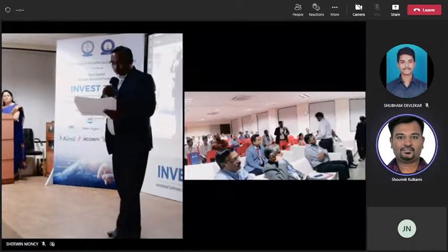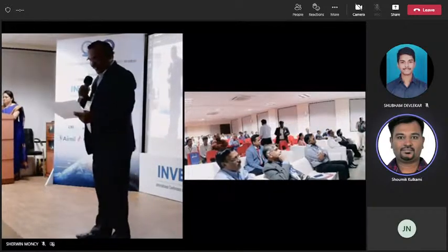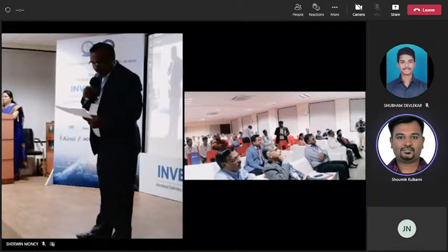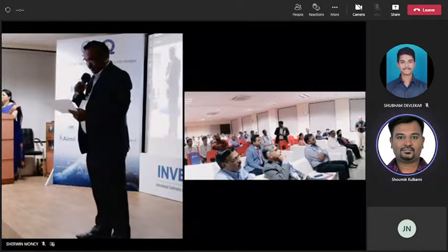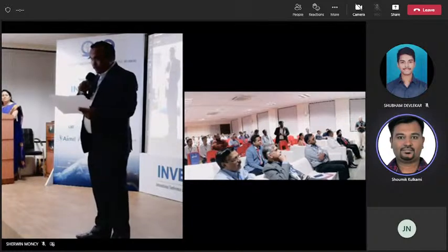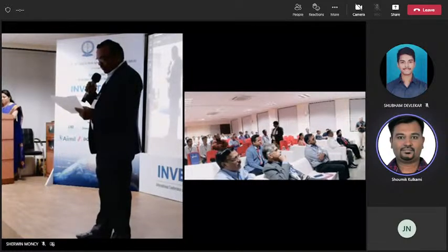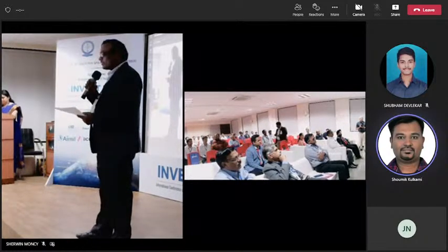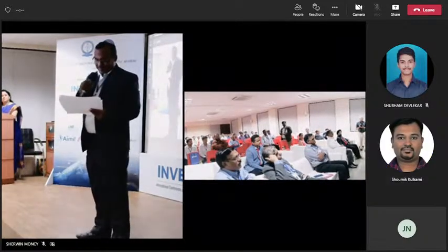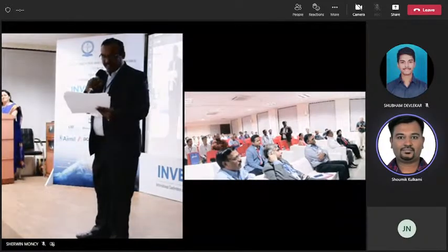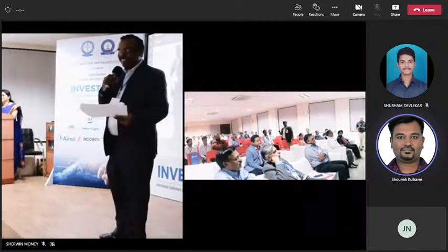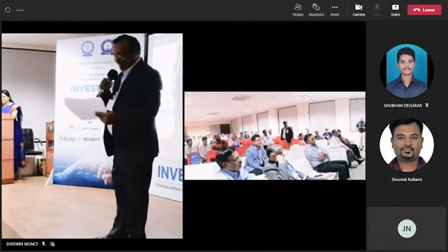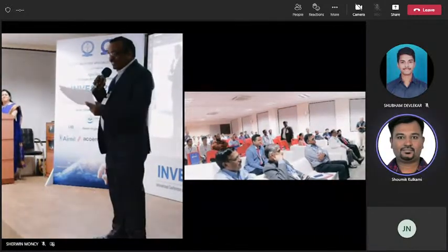There is one more coupon, so we will ask one more question. Other than Professor Shamim Pathan, will anyone answer: why is a half bridge circuit preferred over a quarter bridge circuit? One reason is temperature compensation. Another reason: it also provides higher bridge sensitivity.